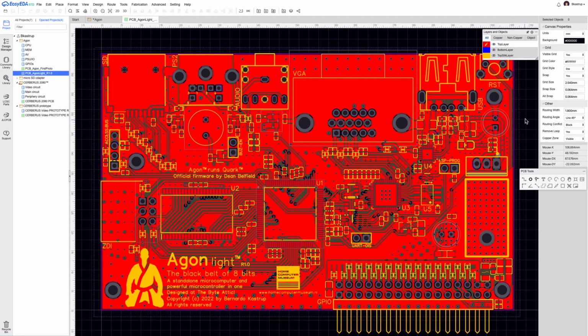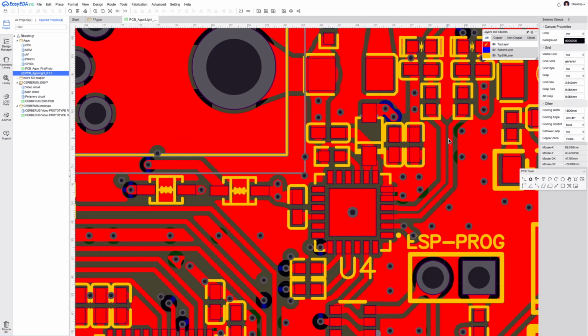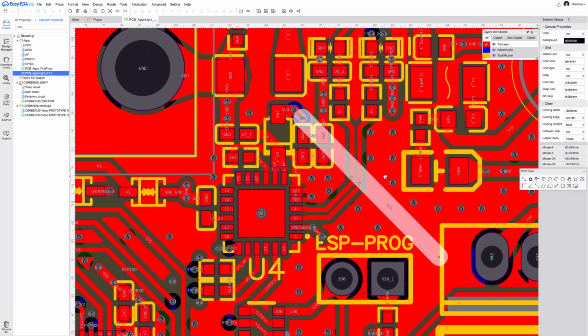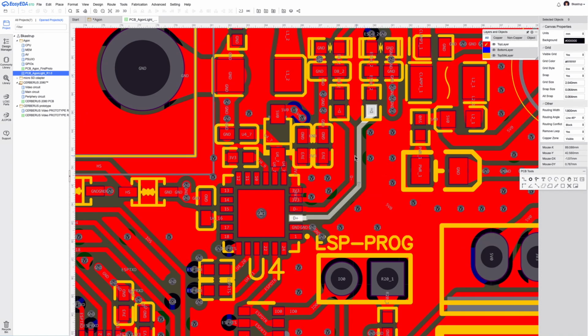Now let's first get ourselves oriented on what is where. This is the USB port. This is just that filter for the USB signal that you've seen. That's the differential pair, D plus and D minus. Notice that they are routed as close together as the design rules would allow. And the reason is that because this is a differential pair, D minus and D plus, you want them to couple to one another. You want there to be common mode here because it will help filter out extra interference that has nothing to do with these two signals.